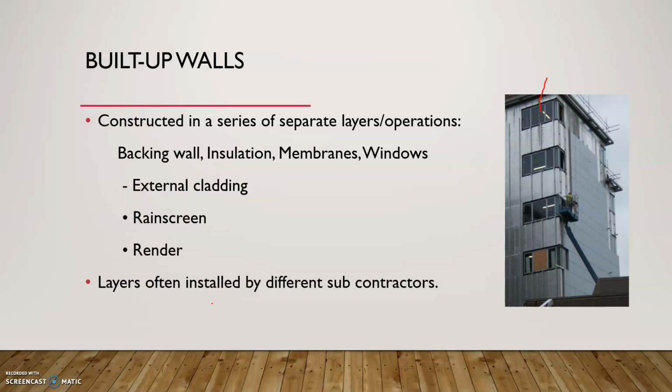Layers are often installed by different subcontractors. So usually you have one subcontractor for the backing wall, which could be SFS or concrete wall, and then another contractor for Rainscreen cladding, and maybe another contractor for windows and doors and curtain walling. Generally they use standard components.